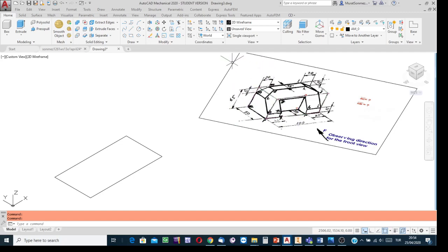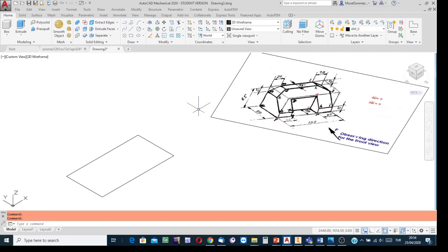This orientation is suitable for me. If not, then apply 3D rotation again. Now, this is the profile. I am sure the bounded area by the rectangle is a closed profile and it is ready, okay, it is a region. No need to apply region definition process.